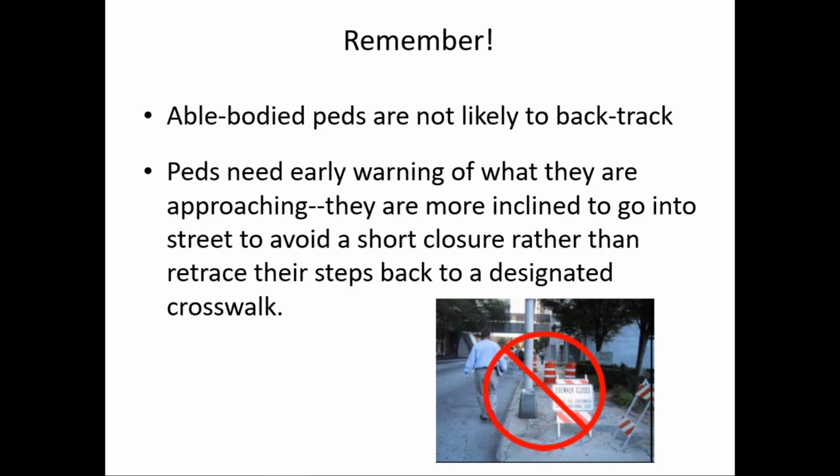But remember, a person in a wheelchair with an assistive device can't get to the street because there's no curb ramp. So they're going to have to backtrack and turn around. A blind pedestrian who encountered this location, once they figured out what was going on, because without a detectable edge it's not immediately obvious that the sidewalk is closed, would also have to backtrack to, say, a corner and then reestablish their bearings and figure out how to proceed from there.